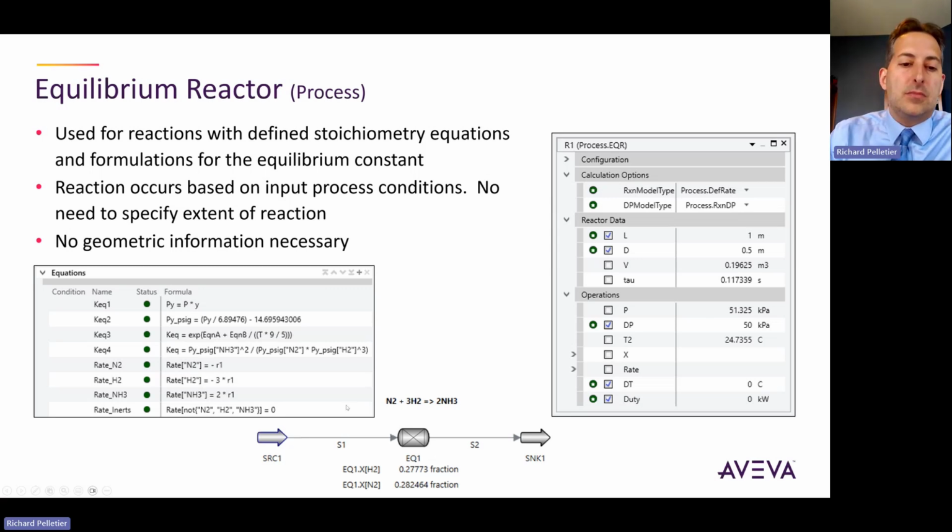So when you see your reaction submodel, you see equilibrium or kinetic data, and then you see rate information, which is all stoichiometry based. Don't be concerned that it's not utilizing your rate or kinetic data properly, because that's not where it's happening. It's happening in the reactor itself, where those relationships implement the kinetic and the equilibrium information.